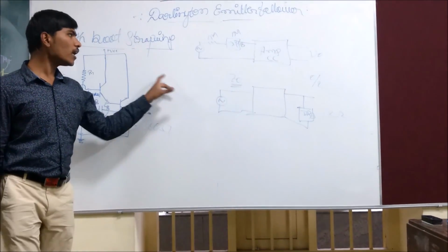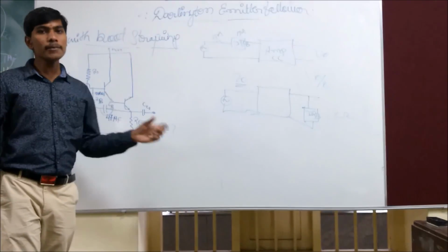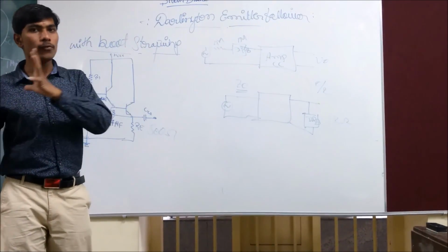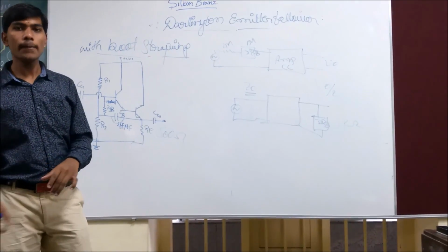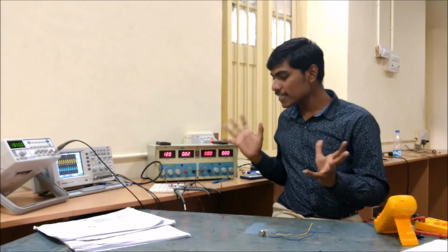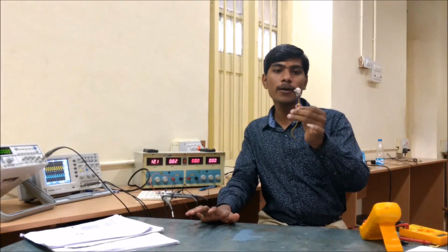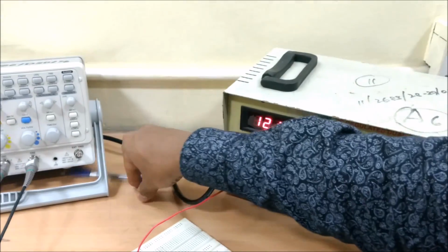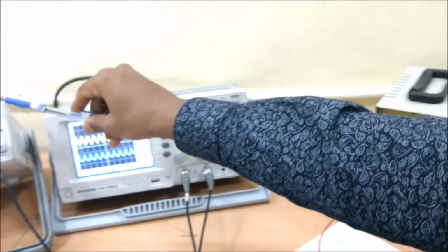Okay, this is all about how to measure impedance and gains. So let me show the practical case of how we will calculate and extract these components. Come back to the practical session of the emitter follower. I'll use a 1 mega ohm pot, plastic package. Guys, it's a 12 volts VCC. You can see it's an RPS 12 volts VCC, and then an oscilloscope.